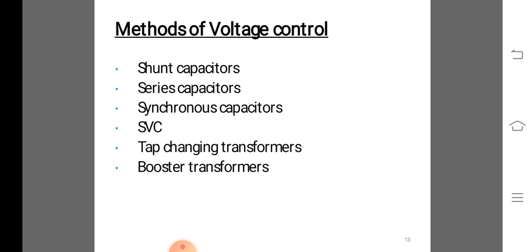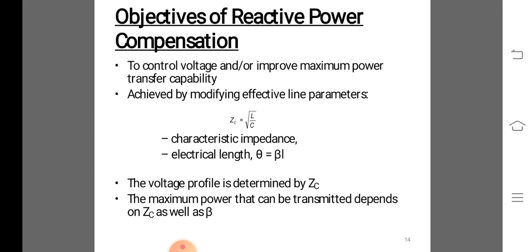Then the primary winding is star connected with the neutral grounded, suitable to the thyristor network. The secondary reactor is normally non-existent, as it is more economical to design the reactor transformer with 200% leakage impedance between primary and secondary winding. The delta connected tertiary winding will effectively compensate the triple harmonics. The capacitor bank is normally subdivided and connected to the substation busbar via one circuit breaker per subbank.